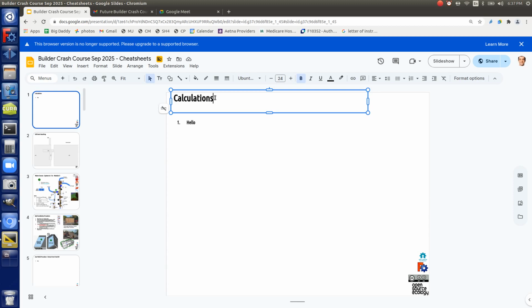Okay, before the 3,000, I was at say 2,500 or 2,000. I convert that number into actual pounds per square inch pressing on the block, based on having a 5-inch hydraulic cylinder and a 12 by 6, 72 square inch press plate. So all that pressure, 3,000 times the area of a 5-inch diameter, spread across that, turned out to be between 300 and 1,000 or so psi. That's how we measured it. So back to the practical question: if those bricks are 300 psi, we're talking dirt. It's less than concrete, absolutely, but concrete is only 3 times as much in terms of compression strength.